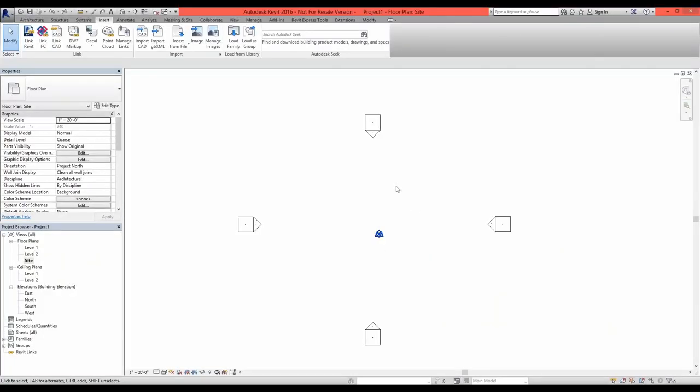And so right now I've just started a Revit project. This is just the basic architectural template. There's nothing all that special about it. You could start from any template that you prefer. The only thing is that we need to be on a particular view that can see topography. So in this example, in the architectural template, if we go to the site plan, that actually has its visibility and graphics to show all topography, and its view range is set appropriately so that we can see all of that different information that we might be laying out.